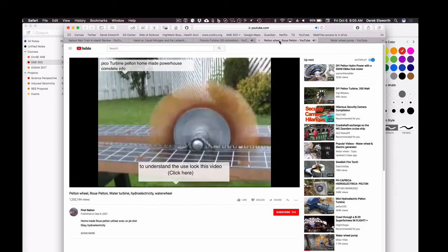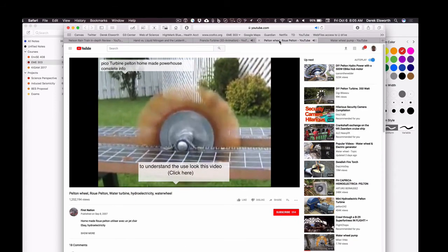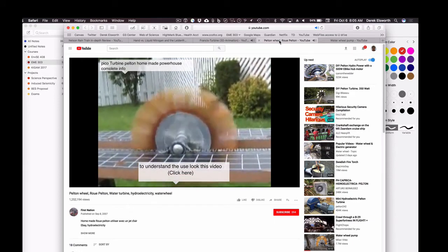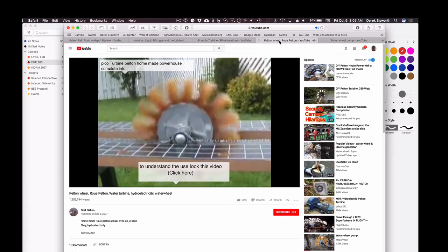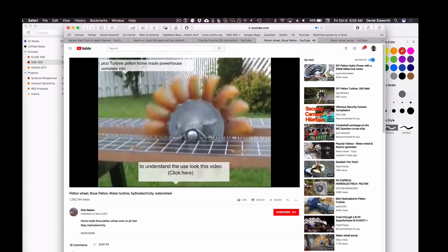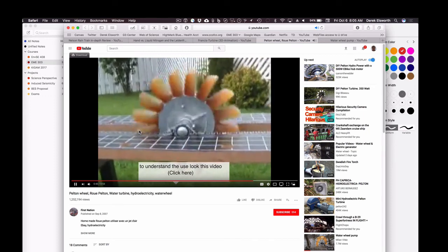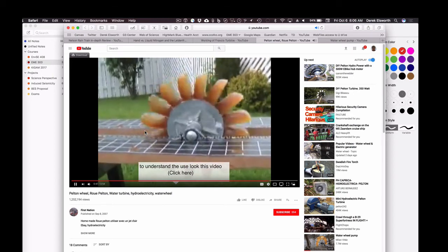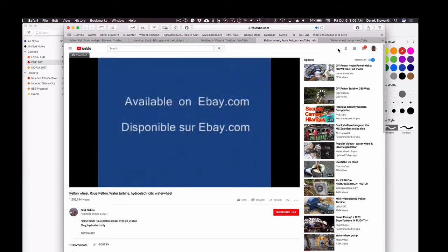Pelton wheel we've already looked at. Same principle, just a bunch of cups destroying momentum. You could imagine that if you hold that Pelton wheel static, you have to have a torque applied to it because it's trying to twist. And if you let it go, then as we'll see today, if it's frictionless and weightless, the velocity it moves at is the speed of the fluid which is hitting those individual cups.